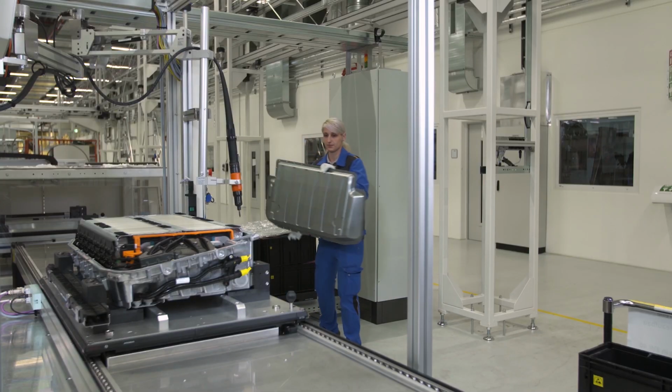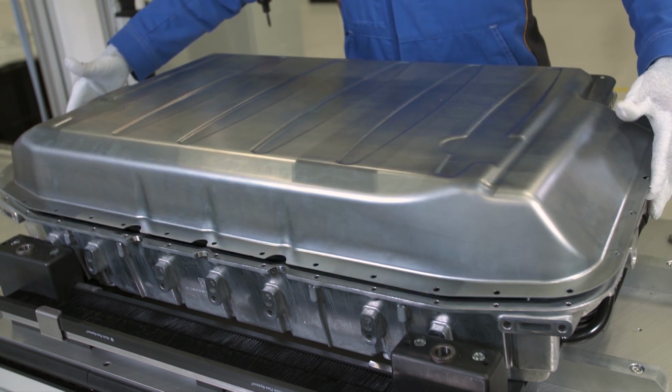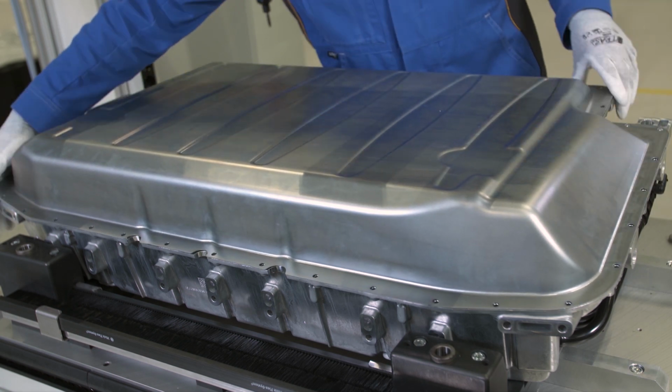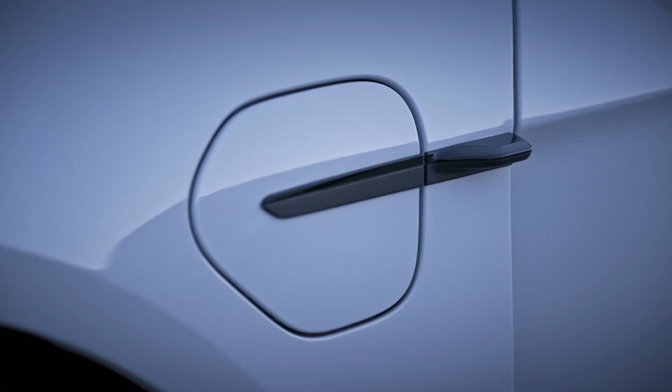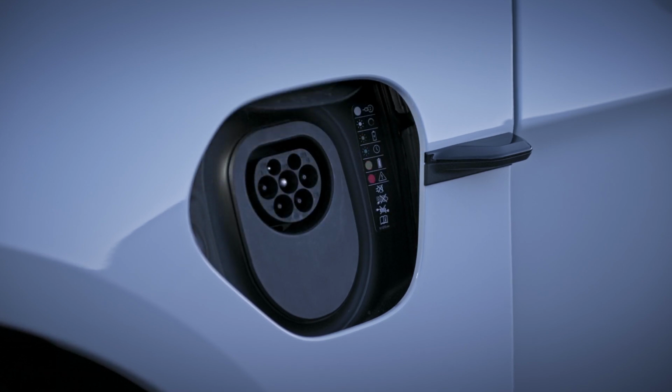Let's take an example to illustrate. Most EVs on the road now have a battery pack voltage around 400 volts. Teslas might be 350, others may be more. But there are some manufacturers that are rolling out 800 volt systems. The Porsche Taycan is one that springs to mind. But more recently, the likes of Hyundai and Kia are making cars with 800 volt systems. But drive those till they're almost empty and you won't see anywhere near 800 volts on the readout of the charger when you plug it in.